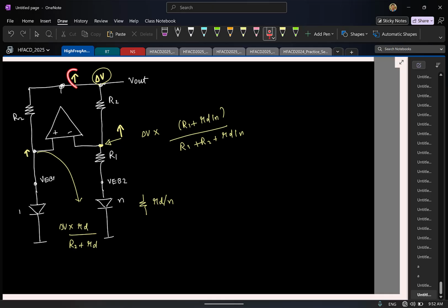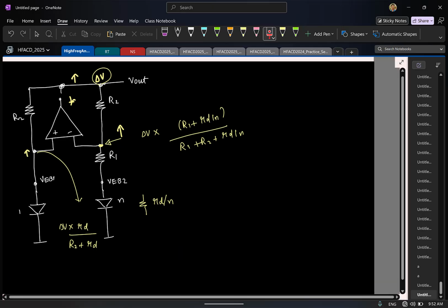I increase this, my inverting terminal increases more than the non-inverting terminal. So will the output of the op amp increase or reduce? The output will reduce, which means we have negative feedback. So anytime you have a case like this where you have both negative and positive feedback, make sure that the negative feedback dominates, especially at DC. That is very crucial. The way we derived the circuit, you don't have to worry because the signs came organically, but otherwise you should check this. So let's try.